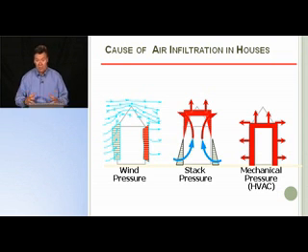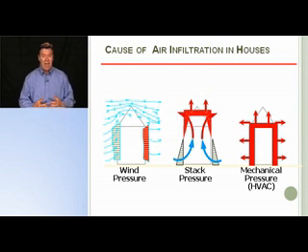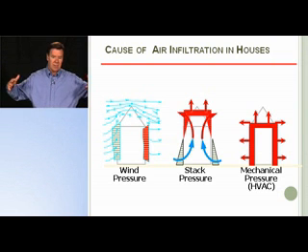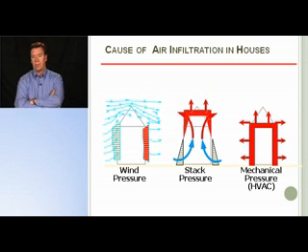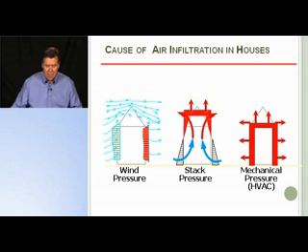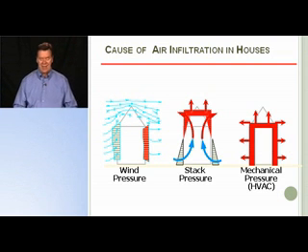That's how attic ventilation works. In other words, we have air that goes in through the soffit vents. It gets heated in the attic, it rises, and then goes out through either the ridge vents or gable vents or pod vents at the top of the attic. But that's heat transfer by the stack effect.